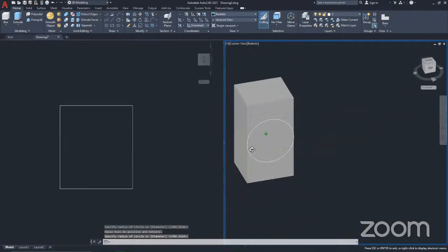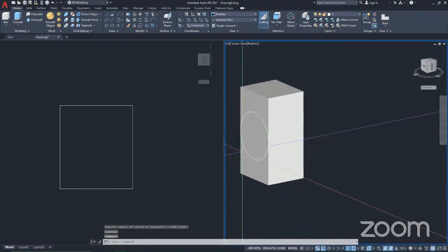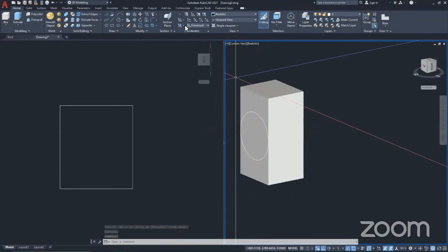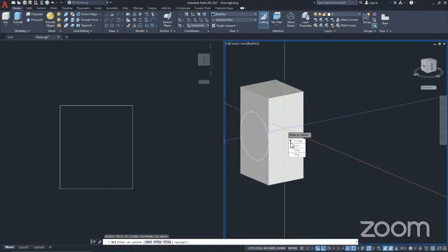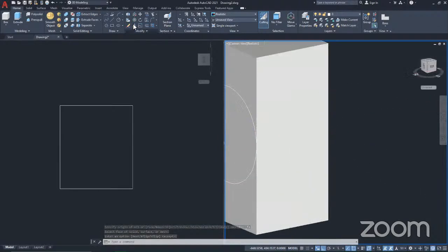So now you see, because it was aligned to that plane, we can actually draw on that plane. Now let's say we want to make a drawing on this face. We'll go over again and come to the face, and then select the face we want to draw on. In this case, this face, accept it. Now, having accepted that, you can now draw on that face. Let's say you want a polygon of 6 sides.